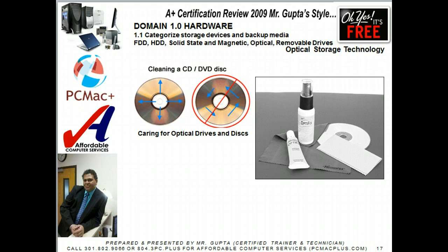To clean the CD-ROM drive, we recommend purchasing a CD-ROM cleaner from your local retailer, such as a local Radio Shack. Using a CD-ROM cleaner should sufficiently clean the CD-ROM laser from dust, dirt, and hair. In addition to cleaning the drive with a special disc designed to clean drives, make sure, however, that the tray has been cleaned.